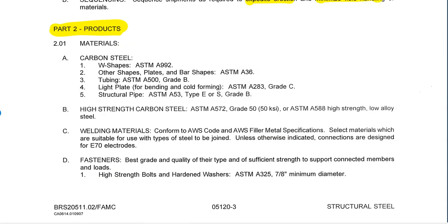When we get into products, you're going to see that there is a definition in the AISC Code of Standard Practice of what structural steel is, and here we're very specific. So when we're talking about carbon steel, this is where we give the grades, and again, these are industry standards. So typically W shapes are ASTM A992. The rest are usually going to be A36. Tubing comes in this grade here, etc. So you can see how this is where, if there was some specialized steel, it would be designated right here. If there's high strength steel, this would be specifically indicated on the drawing somewhere.